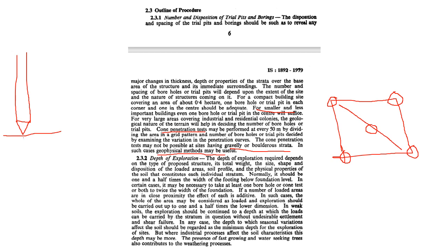So you will just keep going into the subsoil profile, and wherever you stop, you can get the tip resistance, or you call it the cone resistance. There is a sensor here, so you are basically penetrating into the soil. As you penetrate, the soil gives a resistance against that penetration, which will be measured as the tip resistance or cone resistance.